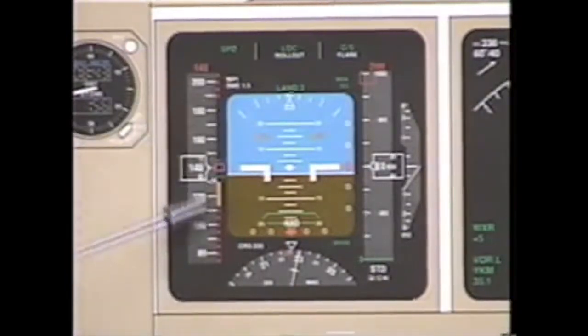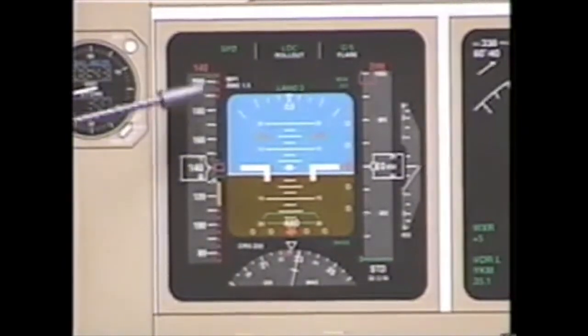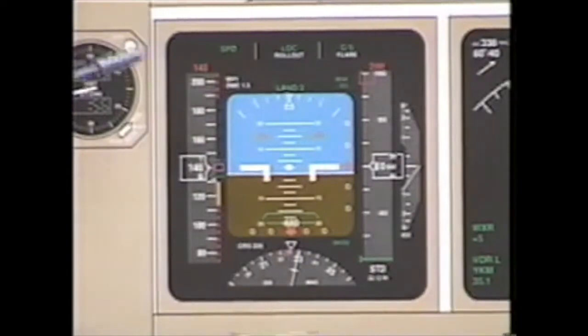A vertical tape for airspeed. Your indicated airspeed is always indicated here in the center. Your target airspeed is always indicated at the top in magenta. Keep in mind your target airspeed can either be MCP or FMC driven. In either case, it will show up in magenta. To determine if it's MCP, you look at the MCP airspeed window. If the airspeed window is open, with numbers displayed, that target airspeed is MCP driven. If the indicated airspeed window is closed, no numbers, the target airspeed is FMC driven.